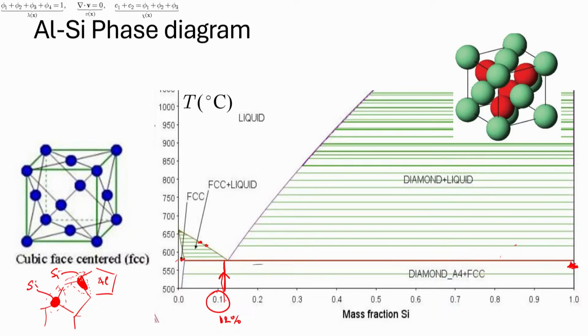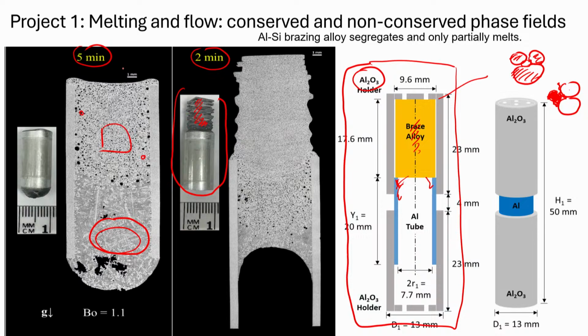And if you kept all the liquid confined, the silicon would diffuse, and in the end everything would melt. But if you take away silicon rich liquid, then there's no silicon to help aluminium melt. And these grains here, these are the grains that have never melted. The grains. Those little white dots.